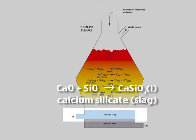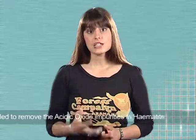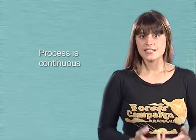It is molten and runs to the base of the furnace. Calcium silicate is used in the construction industry to make breeze blocks. So, limestone is added to the furnace to remove the acidic oxide impurities in hematite. The process is continuous. More raw materials can be introduced at the top of the furnace as iron is tapped off at the bottom. The iron produced in the blast furnace is impure.